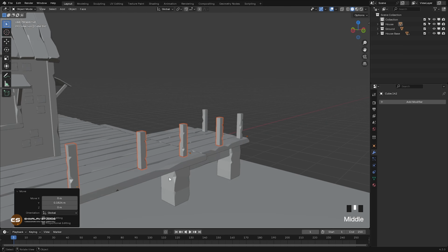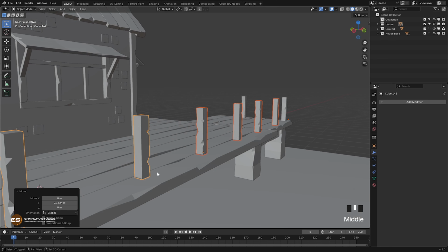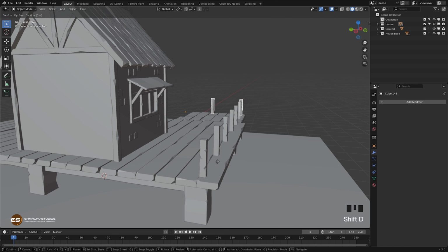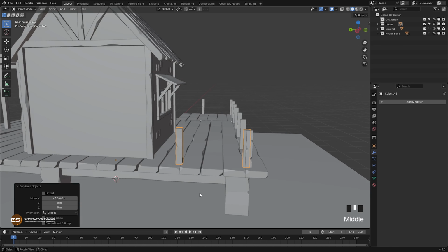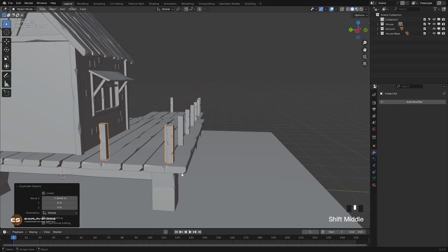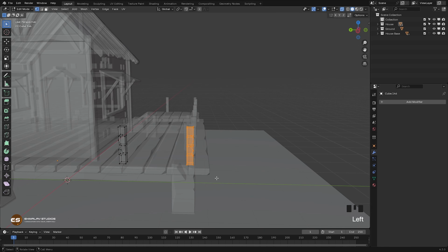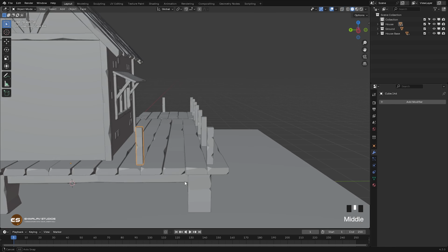that should be fine. And if you look at the detail, they are again the same, so probably you want to add some change to some of them. So copy this one again, and this time I'm just gonna delete this one. So tap to go in edit mode, Alt Z, select this one, and X and faces, and Alt Z, tap to get out of edit mode.